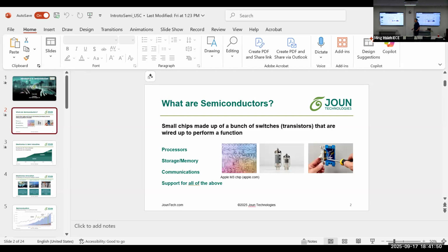Yeah, I think that's a great question. Well, I'll just explain. On one of the slides, I talked about the introduction of new materials. Silicon on the base wafer has been around forever as the mainstay. But increasingly you see two big ones, gallium nitride and silicon carbide. Gallium nitride, by the way, came out of the LED lighting business, and has the ability to handle very high temperatures reliably. Silicon carbide also has similar properties. So that's one intersection point that's really important today, and again, the diversity of demand is driving that.